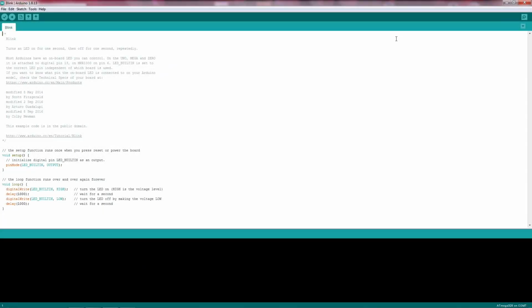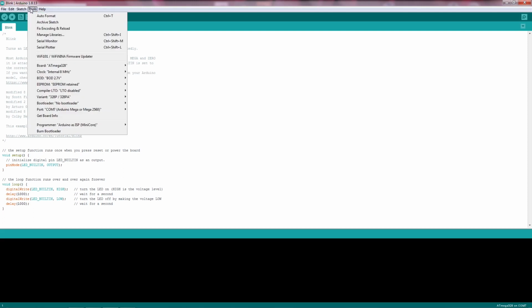So, the way you configure your microcontroller to run with an external crystal is very much the same as you would configure it to run with the internal oscillator. You have your Arduino IDE with the MiniCore, and in the tools menu you have the options you set. Once you set your board to the correct one, which it already is, you then have all the other tools from the MiniCore. Everything else here works pretty much the same as in our last video. So don't forget the port, don't forget to have the programmer correct, that's all the same.